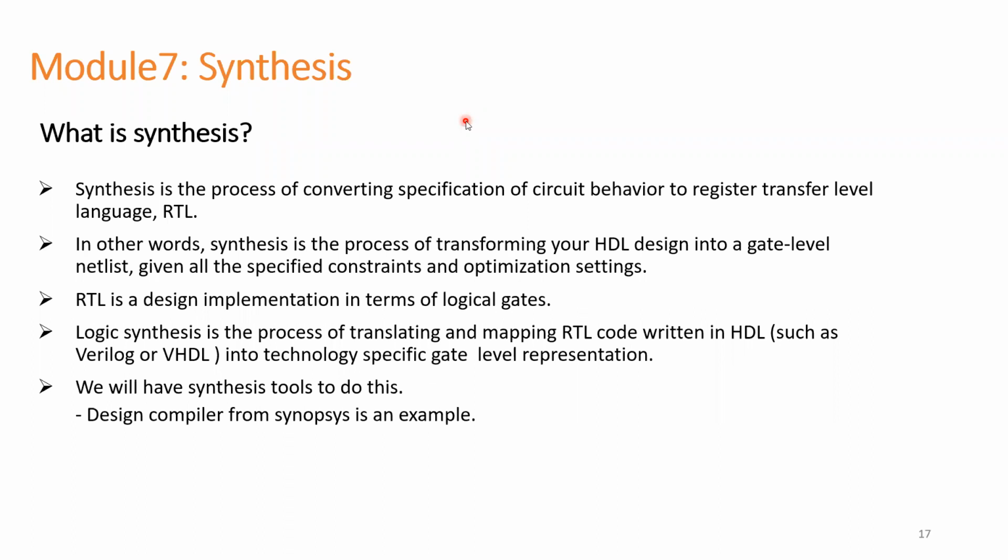Let's say one AND gate is there, and the output of the AND gate is Y. The Y pin will be connected to an OR gate, to some pin X1 or X2, it can be any name. There will be a wire name between Y and X1, so it can be N1. Like that, all these connections will be written inside the gate level netlist. So that is about the gate level netlist.